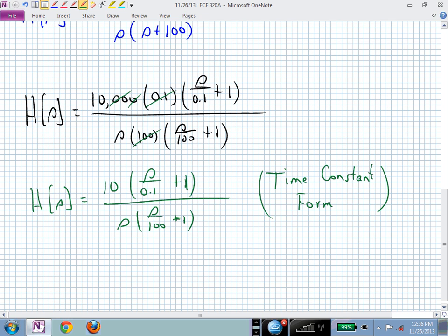It's the value that's multiplying that s in its factor. So it's 1 over 100. It's 0.01. It's 10 milliseconds. That's the time constant associated with that pole at s equals minus 100, if somebody asks you. And then how long would you have to wait for your transient to be gone in this circuit? 5 of those. So 5 times that 0.01, or 50 milliseconds.